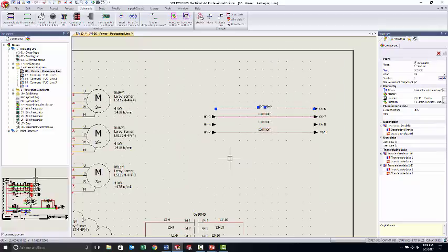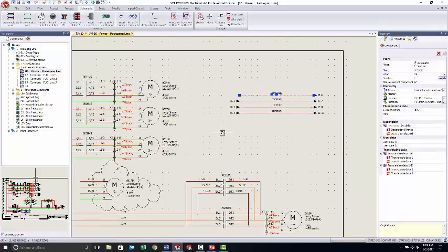Yeah, I've got a couple of different customers that do that. They do that with the 24-volt DC. Rather than having separate numbers for all of it, they call 24-volt DC their common main power. They call that all one wire style. And anywhere that's at, it is all connected up on a terminal strip, and they just distribute it. And so, again, this would work for that.